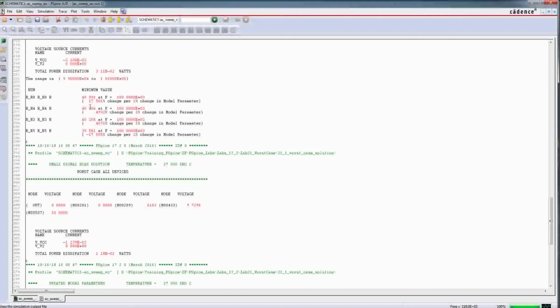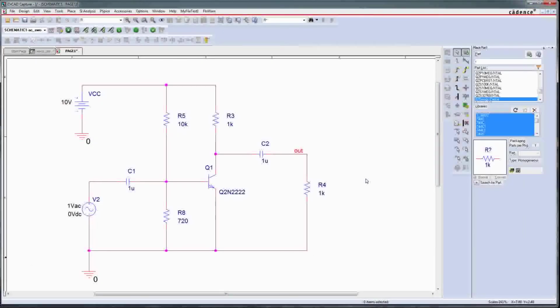If they are really sensitive, then we have to use components with small tolerance, and those which have low sensitivity, we can use with high tolerances. Why? Because they are cheaper and we can reduce the costs of our designs. That's the advantage of the sensitivity. And also, for the worst case, it helps to detect the requirements and goals we want to reach.